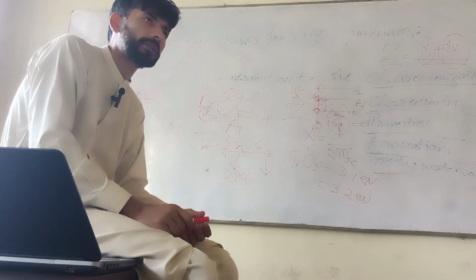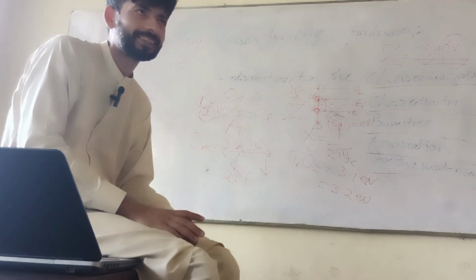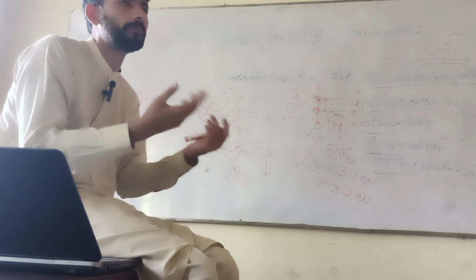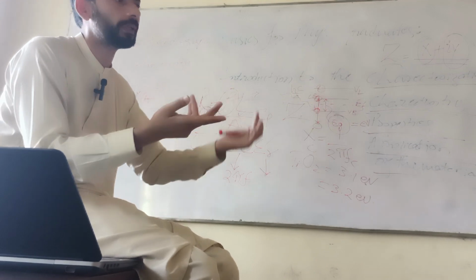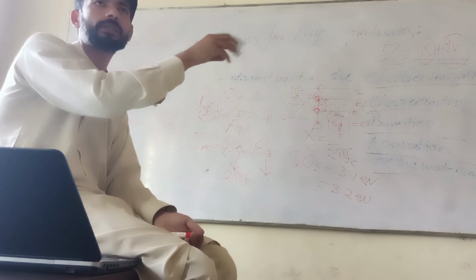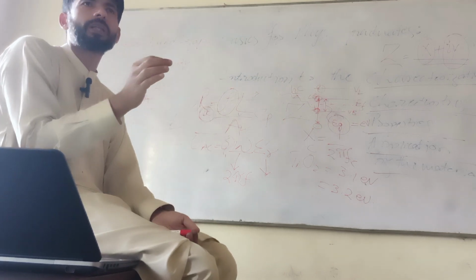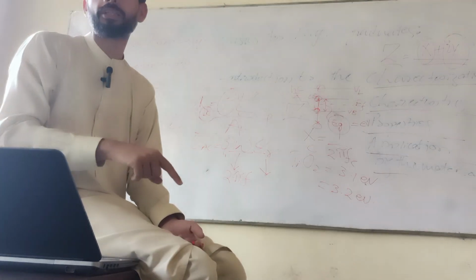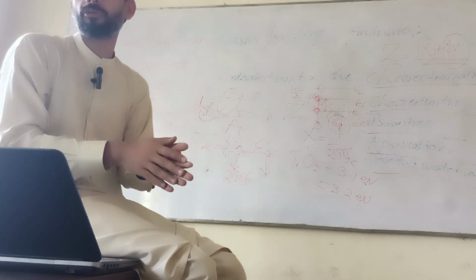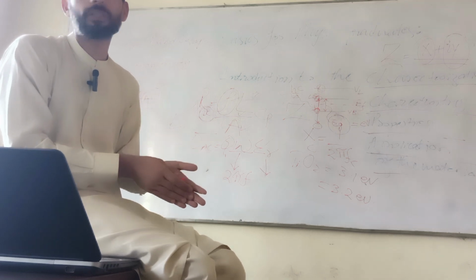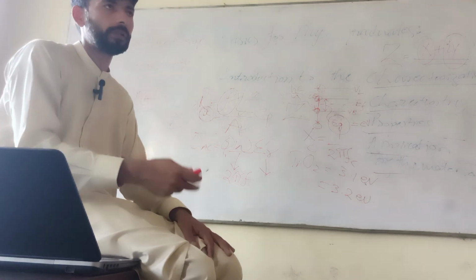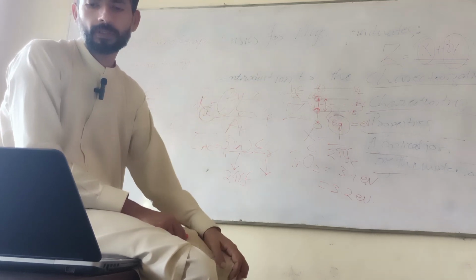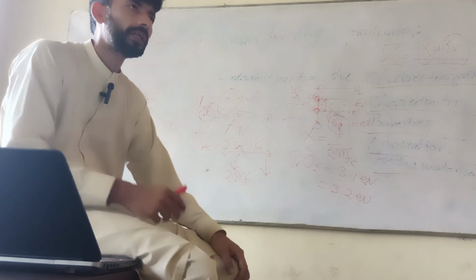Then the elemental analysis, EDX, just elemental analysis. For example, if you blend some elements into some kind of material, for example titanium and something else, and the quantity is very small, and the XRD was unable to verify that there is titanium inside your composite, then what do you have to perform? EDX. Maybe it will identify it. Or there are some other applications of EDX. XPS analysis, XRF analysis,